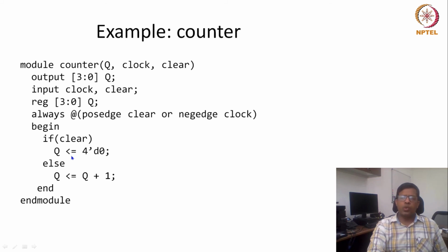So usually non-blocking assignments are preferred in the case of flip-flops or flip-flop-like structures, and they're also preferred whenever we are trying to model a data flow or combinational logic.